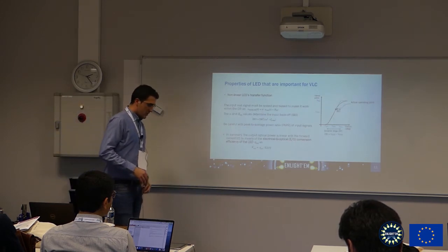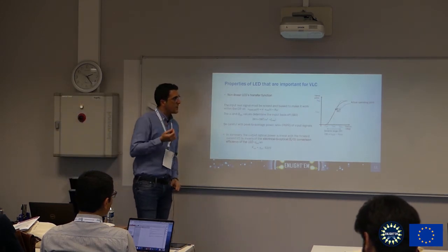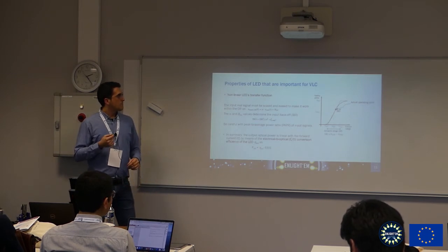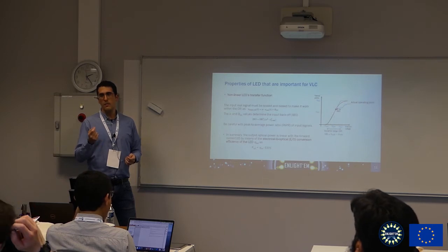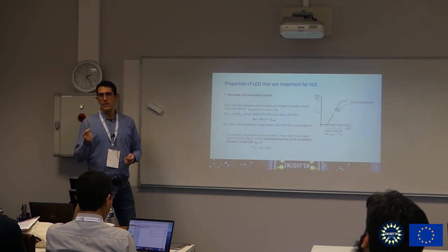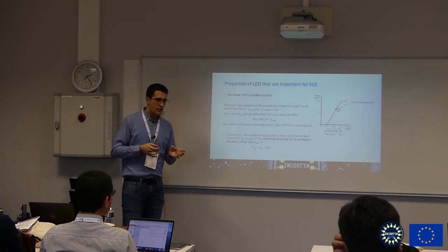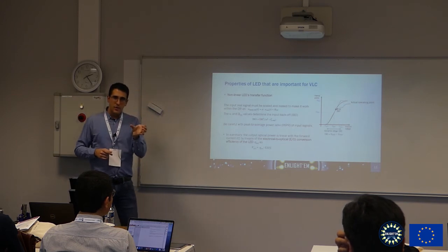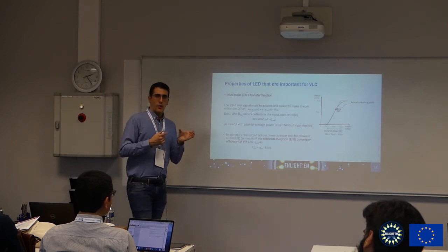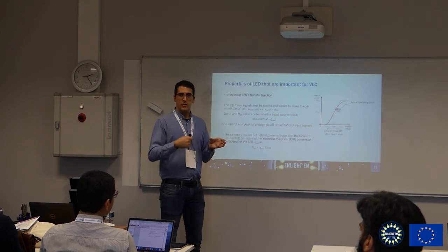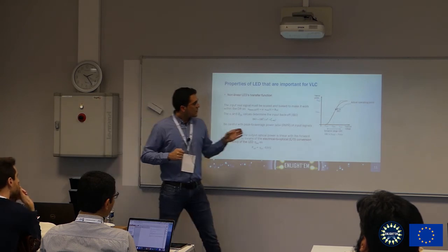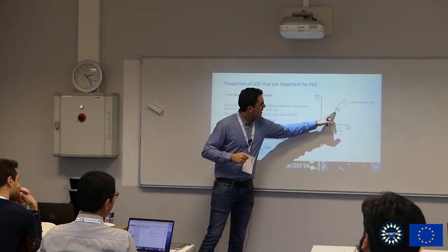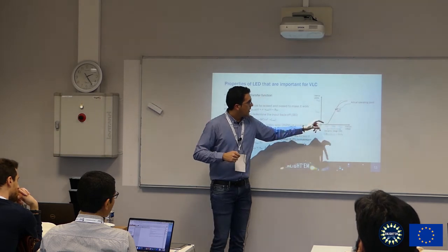Also it's very important to know that the transfer function of an LED is similar to that of the high power amplifier in radio frequency technology. We don't have a linear response of the transfer function, so we have to be careful and try to work within the dynamic range of the LED. Otherwise, we will create some distortion in the transmitted signal, which will be really difficult to detect at the receiver side. So basically we have here a linear range of the LED, and we should try to work